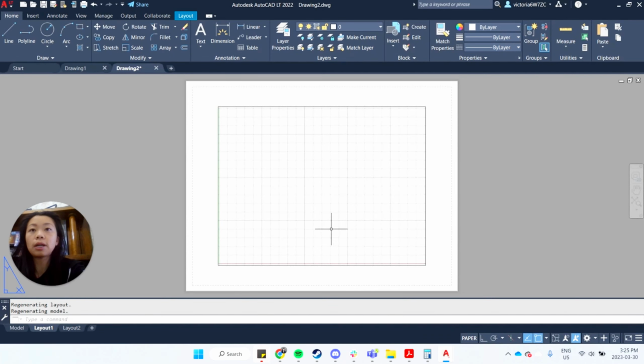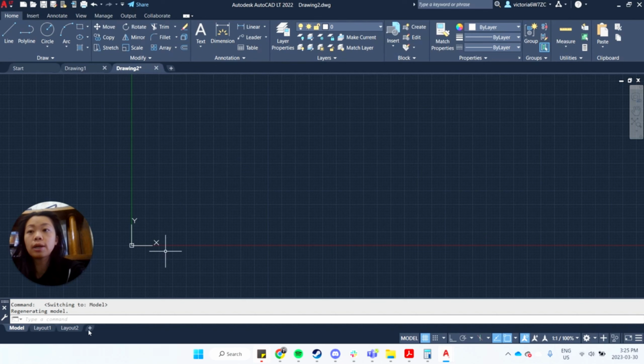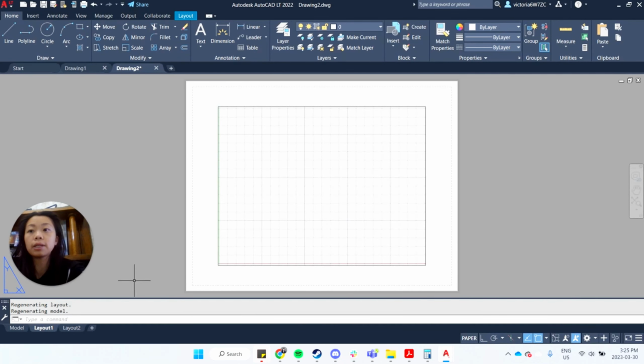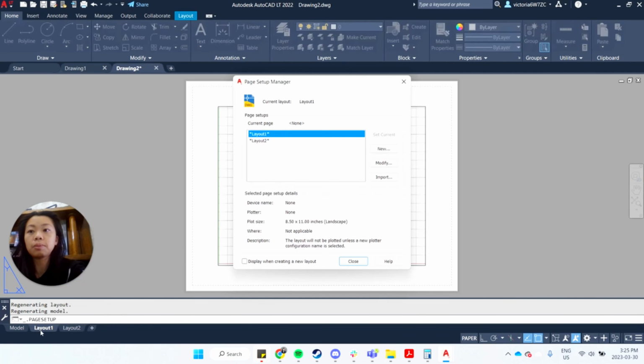This is where you can set up the page size. You can set up what scale you're going to print at. Is that 1-to-100, 1-to-200, or if you're imperial, maybe a 1/4 inch scale, that kind of thing. That way you have to do less math, right? If you're always modeling at full scale, then the only place you should be scaling is in paper space. So know that.